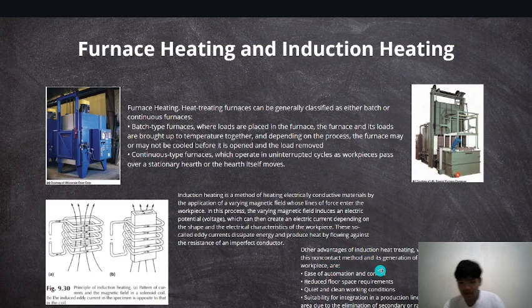Other advantages of induction heat treating, which stem from this non-contact method and its generation of heat within the workpiece, are: 1. Ease of automation and control, 2. Reduced floor space requirements, 3. Quiet and clean working conditions, 4. Suitability for integration in a production line, 5. The elimination of secondary or repetitive heating, and last, self-monitoring capability.